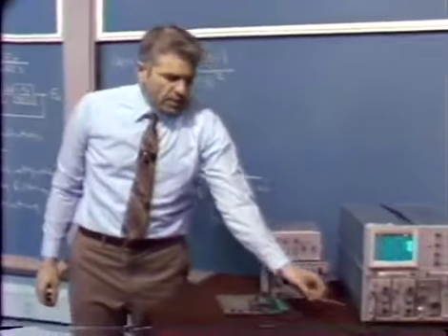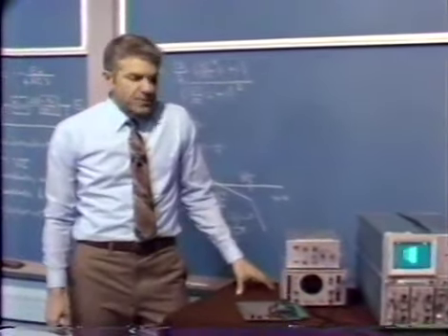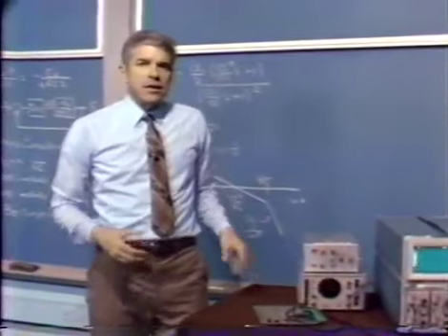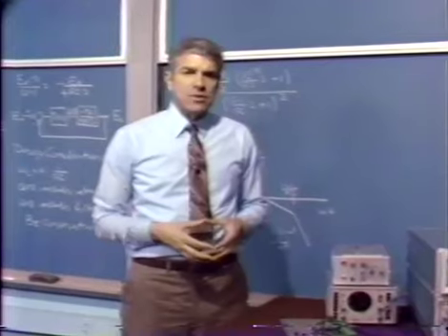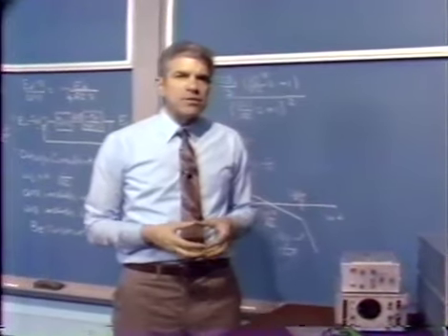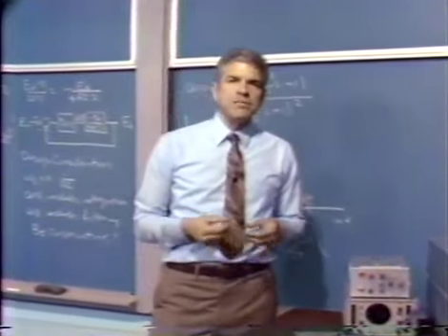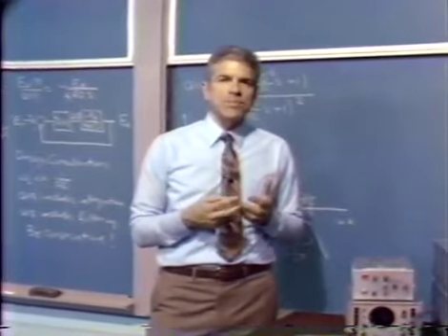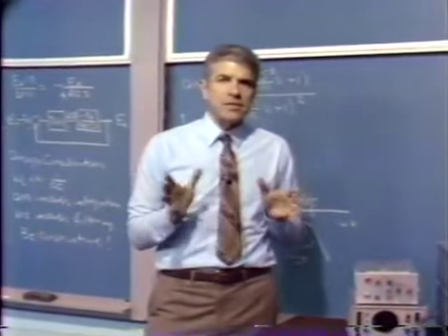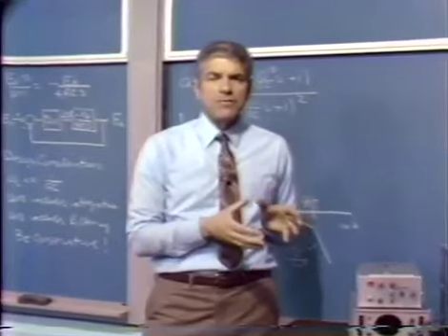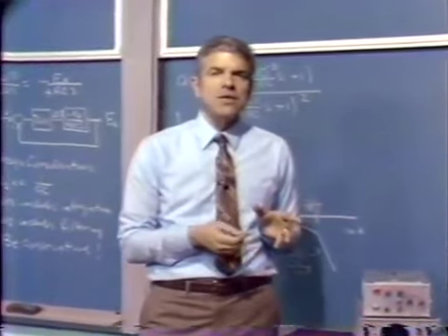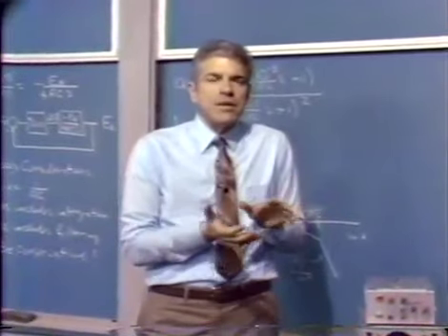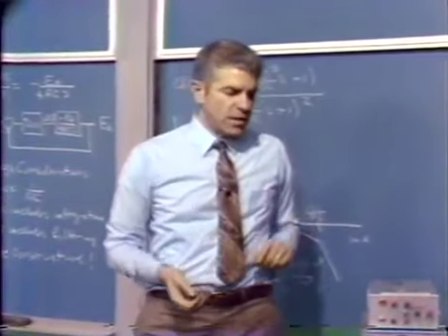In conclusion, I'd like to emphasize that this technique gives us the ability to build a very, very low distortion oscillator, and also is a very interesting example of a feedback system that has two very distinct modes of operation. The basic loop that sets the frequency, the 10 to the 4th radians per second, or 1.6 kilohertz in this case, and then the much slower loop that controls the amplitude of that oscillation.